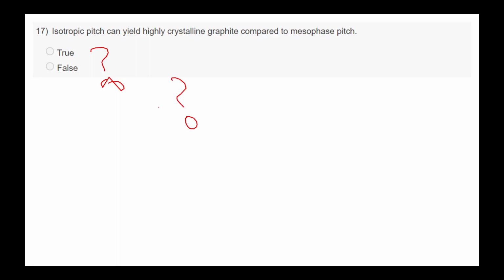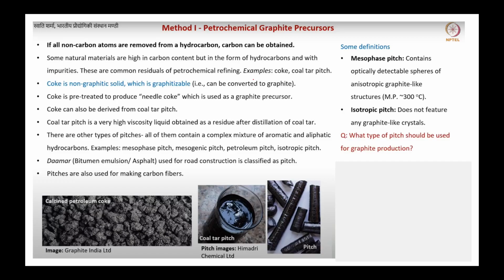Mesophase pitch contains optically detectable spheres of anisotropic graphitic structures, and it does not feature any graphitic crystal structure.